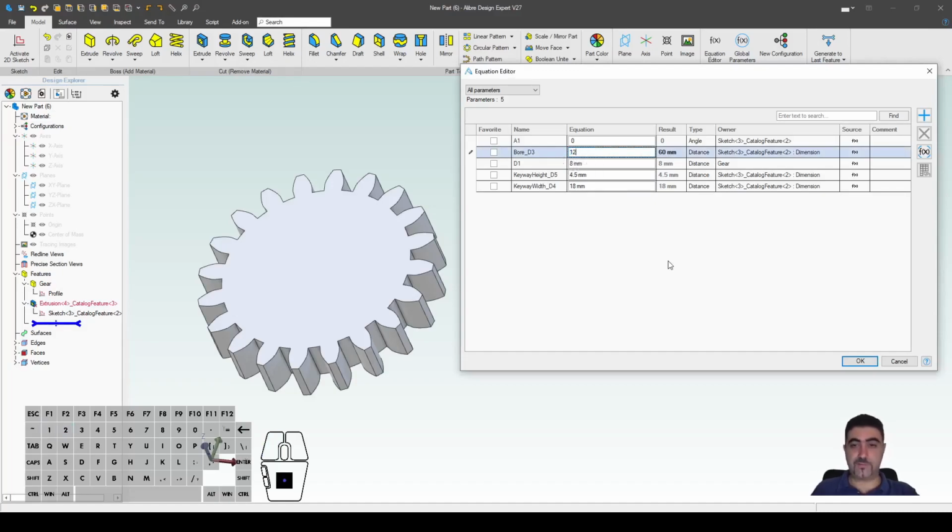So now I want a 12 millimeter bore. And the 12 millimeter bore takes a 4 millimeter key, I think. And I put that 1.9, so give the key, these are small keys, give a bit more bite onto the shaft. So instead of 2, I just give it 1.9.